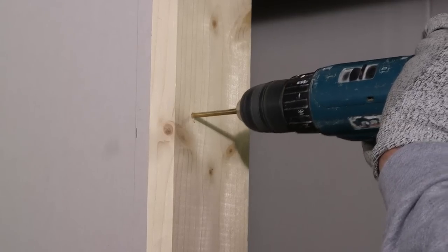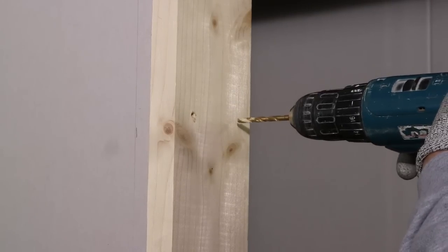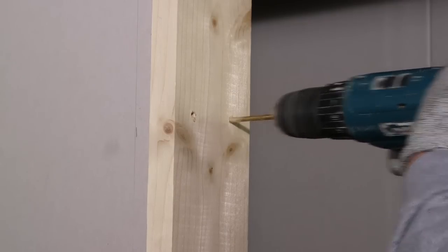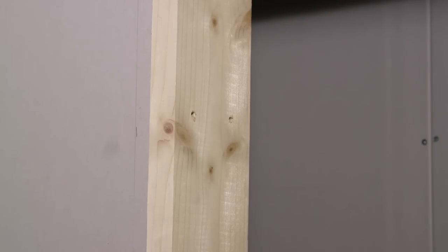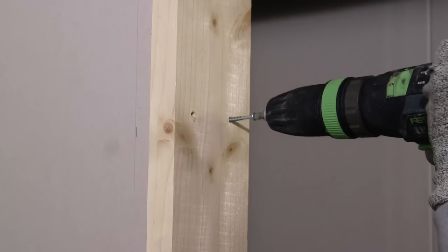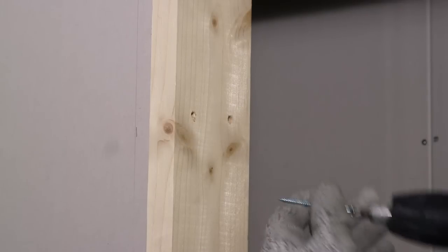Preformed door casings will have fixings guidance information. Where a timber door frame is being fixed, pilot drill 2 holes in 4 positions either side of the door frame. Continue to fix the door frame with suitable fixings, subject to requirements of the door manufacturer.